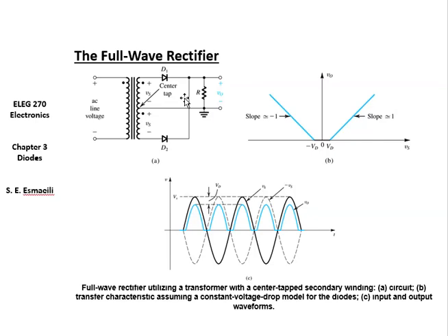One thing that we need to make sure is that the breakdown voltage of any of these diodes must be high enough, because when this 5 comes here, for this diode it looks like -5, right, from this direction. So we have to make sure that with -5 this diode doesn't break.